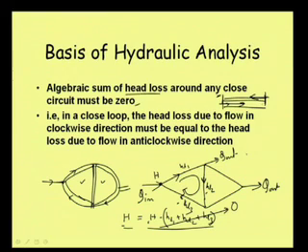The head is more at this point, and less at this point. So, from here to here if we calculate head loss, definitely there is no loss, rather we are gaining the head, and that is why, where the flow is in the anti-clockwise direction, we can consider the head loss as negative.